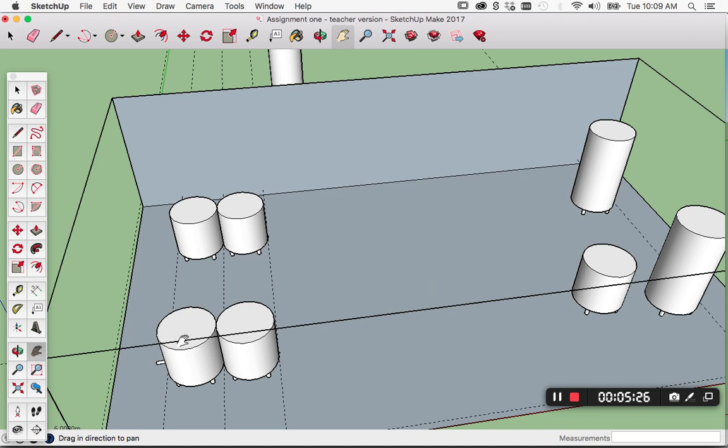So with the fixed line option, it would be from this tank with, let's say, a stainless steel pipe over to the wall, up the wall, along the wall, and then out, essentially fixed to the roof, and then discharging down into that tank from the top. The flexible line option would be along the ground with a rubber hose to a pump, and then over to the base of our tank.